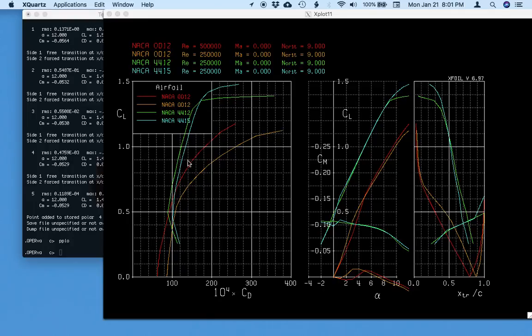You can see that's exhibited here by a slight increase in drag as we've gotten a little bit thicker, but we also end up having a higher lift coefficient at the same value of drag coefficient. So these subtle changes can have a pretty big impact on how your airfoil is going to behave, which allows you to go through basically lots of different airfoils to try to find one that's going to be optimum for your particular design case. Now this was an initial introduction.